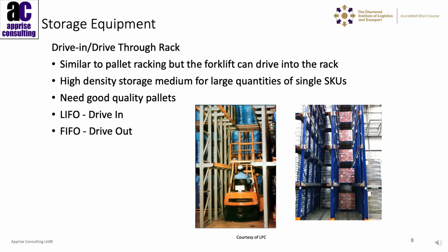This is drive-in racking. You can also have drive-through racking as well. In terms of drive-in racking, the operator drives the forklift truck into the racking itself. We've done away with the aisles here. So the operator will drive into the racking and deposit the pallet on load support rails on either side.